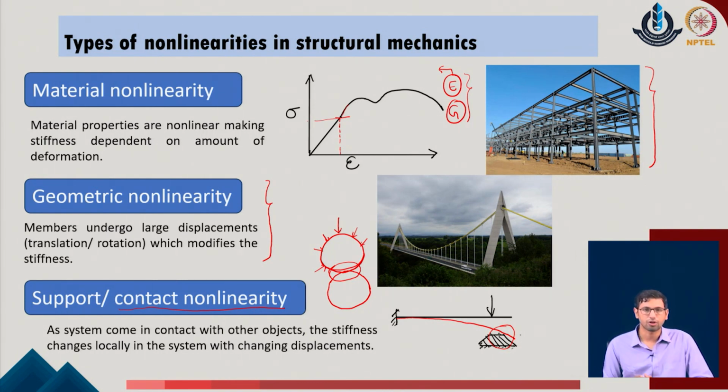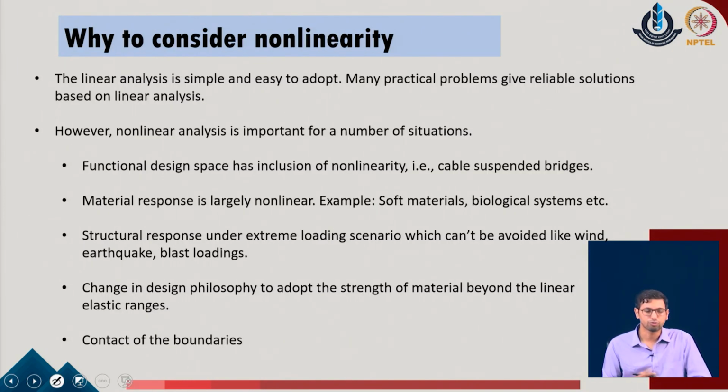So, in our present context of the discussion, we are primarily concerned about the geometrical nonlinearity of the given system. As we move forward, we will also look at the material nonlinearity. Contact nonlinearity in general we will not be considering in this course, but those of you who are interested in doing finite element simulations of these kinds of problems may look into the standard computational tools, and they define the contact nonlinearity very well in their standard algorithms. Now, before going into the geometrical nonlinearity, we must understand why it is necessary to consider the nonlinearity.